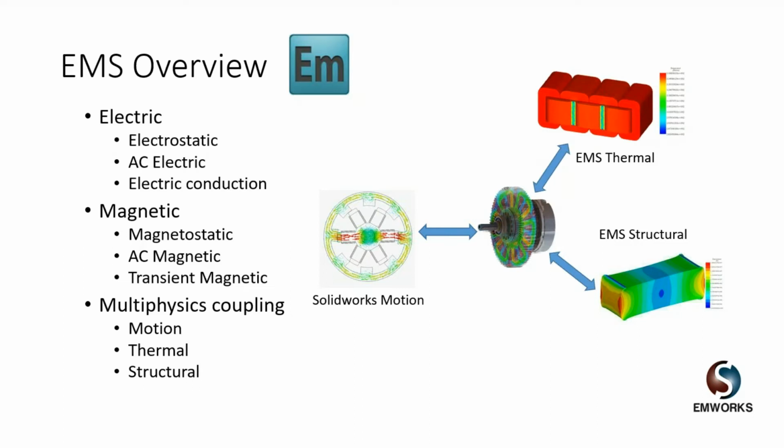In case you were dealing with electric fields which are of sinusoidal nature, which change in time in a sinusoidal manner, you would probably want to use the AC electric solver, which allows you to compute all of the results and values you can get in the electrostatic module, but at the same time you get this dynamic aspect of results.